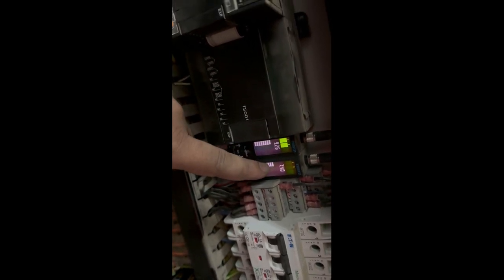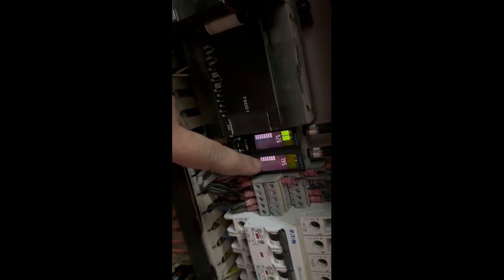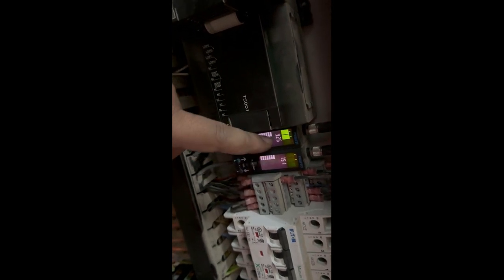And here, neither point A nor point B has been achieved. Once it achieves them, it will again become like this, and it will switch off. This is the thing which tells your compressor to switch on and off on the basis of this input. So this is the input for the PLC, and as the output, the PLC actuates the valves.